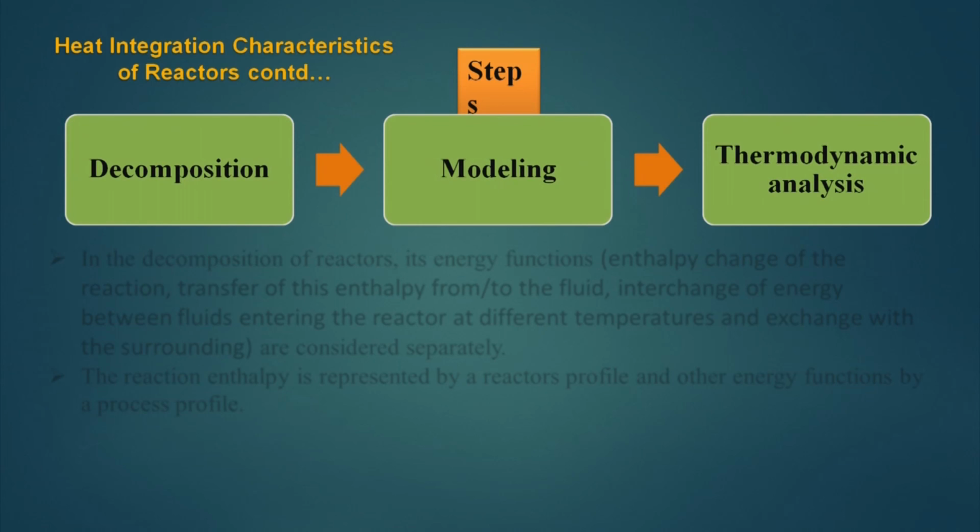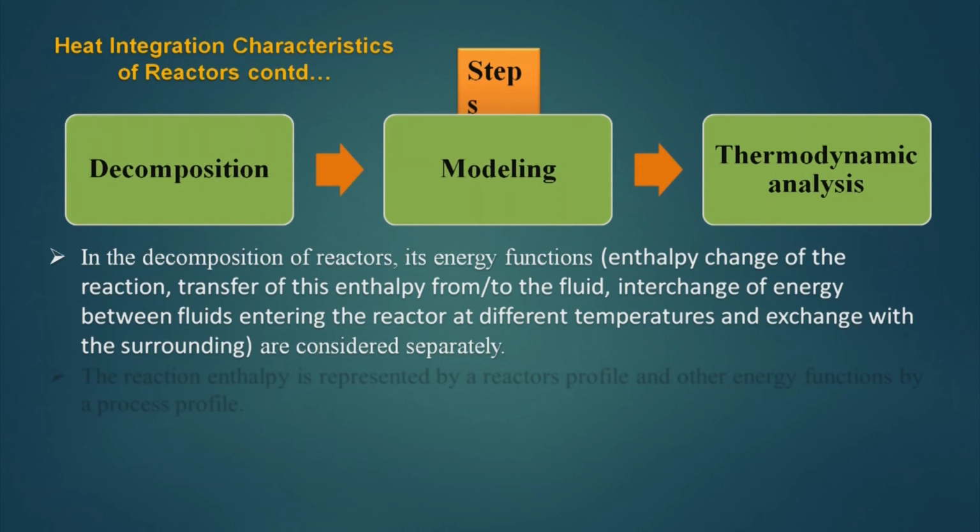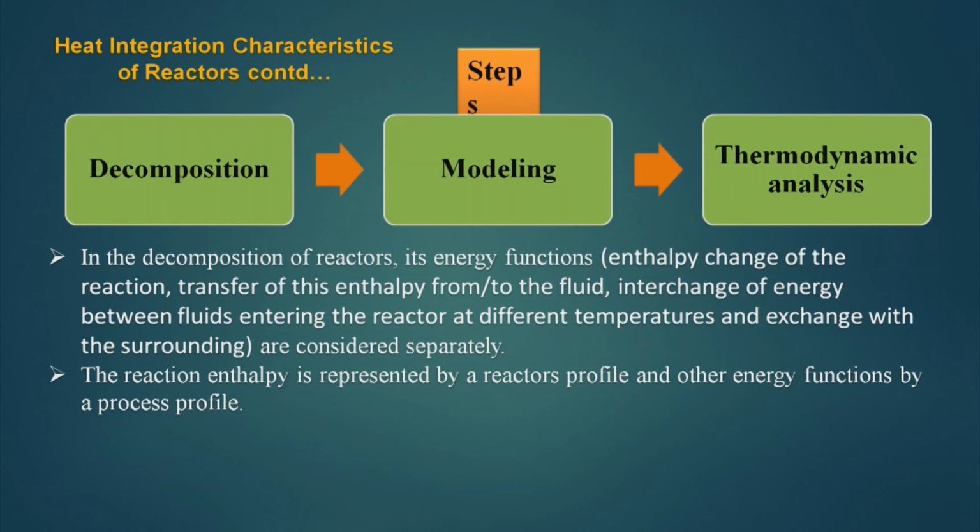Now, the heat integration characters of the reactors can be divided into three parts: decomposition, modeling and thermodynamics. In the decomposition of the reactor, its energy functions, that is the enthalpy change of the reaction, transfer of this enthalpy to the fluid, interchange of energy between fluids entering the reactor at different temperatures and exchange with the surroundings are considered separately. The reaction enthalpy is presented as a reactor profile and other energy functions as a process profile.